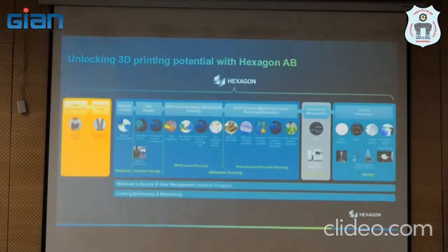We always say that printing is the last stage. Before that we have to thoroughly calculate the fatigue life, durability, then material related properties, manufacturing feasibility and the cost. If I have all the reports ready, then only we go for printing. So this has been the workflow for the OEM. We always look at this workflow as a master chart, but if you are a service bureau, you might not be looking at all of this process.